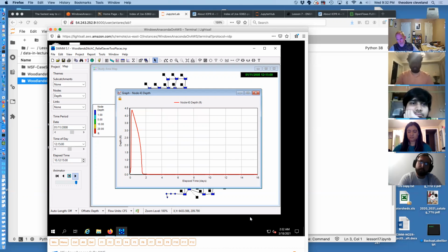So short of sending out a team of disappearing agents to Men in Black them every time it floods, a little flashy thing, that particular release sewer is not a very effective one. And you wouldn't put a 1-foot sewer 800 foot long anyway. That would be stupid. You do something like 2 feet or 4 feet.